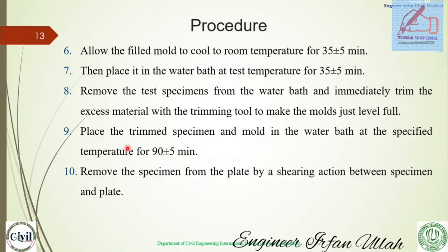Place the trimmed specimen and mold in the water bath at the specified temperature for 90 plus minus 5 minutes. Then again place it in the water bath. Then remove the specimen from the plate by shearing action between specimen and plate.